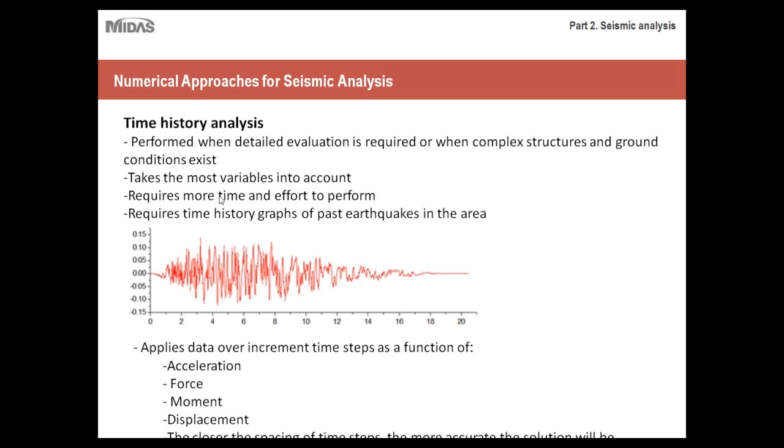It requires more time and effort to perform, obviously, and it requires time history graphs of past earthquakes in the area. And here are the variables that are taken into account as far as your time history functions. It takes into account the seismic acceleration of your loading, the forces being applied to your structure, the moments, as well as the displacements.